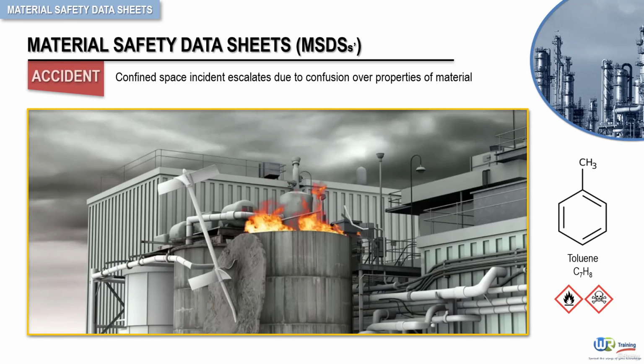The force of the blast blew the top of the tank almost completely off. A flash fire erupted that consumed the flammable gas and quickly burned out. One operator was thrown to the ground and killed instantly from blunt force trauma. In all, 14 operators and contractors were injured in addition to the fatality. An autopsy of the fallen man within the tank indicated that he had died of asphyxiation and inhalation of toluene even before the cutting operation started.